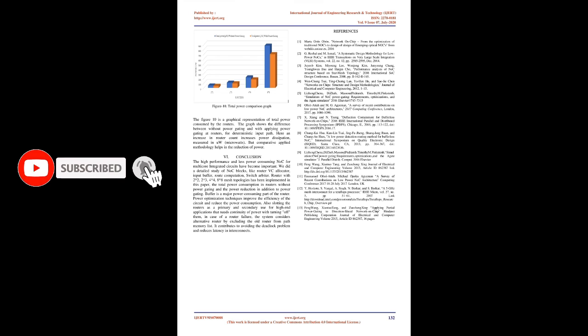D. Route path memory table. The memory table stores the shortest path information from the source router to the destination router. For on-chip networks in the core, there are possibilities of router failures. In that case, the memory table stores the failed router information and prevents other routers from considering the failed router path. The memory table will store the shortest FLIT transmission path to avoid latency and improve efficiency. In case of a router failure, the upstream router automatically finds a new path to reach the downstream router. The updated path will be stored in the memory table.